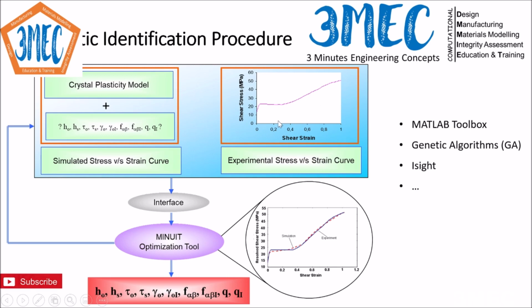So what we did, we had experimental data, we simulated by changing these parameters, and you keep on changing them until we get a good fit. In this case we interfaced ABAQUS with UMAT and everything with an optimization tool. We used a code which was open source at that time, Minuit, and we basically identified the parameters automatically. As you see, it gives a very good fit and a final set of parameters.